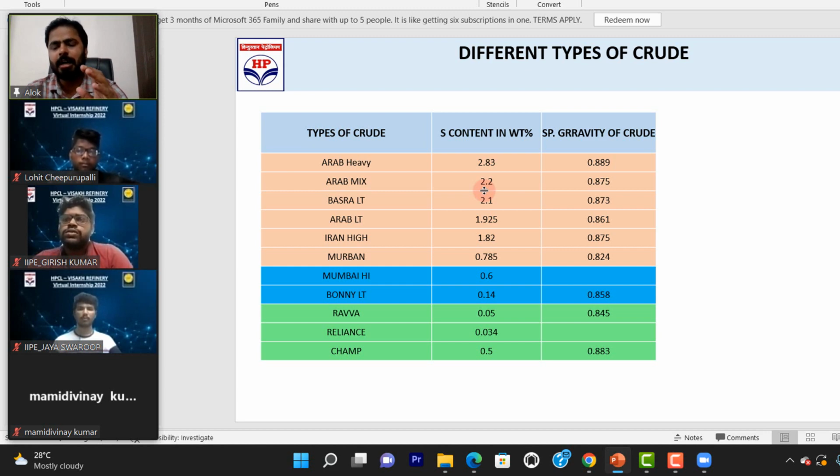So our EOP model, our operation is based on the slide valve. Basically we give a set value of some 510, and based on that the slide valve, RCSV we call it, the regen catalyst slide valve, will open and take the amount of catalyst till the temperature reaches 510 degrees Celsius. So the opening will be some 35 to 40%. Accordingly, catalyst will come into the reactor. Now, how are we maintaining the reactor level? In the reactor also we maintain the catalyst level. That level we maintain around 40 to 45%, in the EOP model.